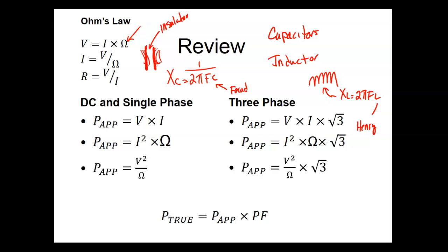You understand that? So if you put DC on an AC relay, it'll burn it up. It'll blow the fuse. Because you don't get any X of L off of DC, right? If you put AC on a DC coil, you won't create a magnetic field strong enough to even pull it in, because now you've got all the X of L. So there is a big difference between DC relays and AC relays.